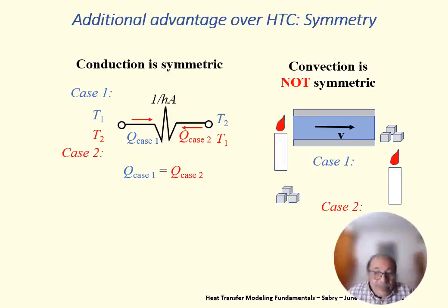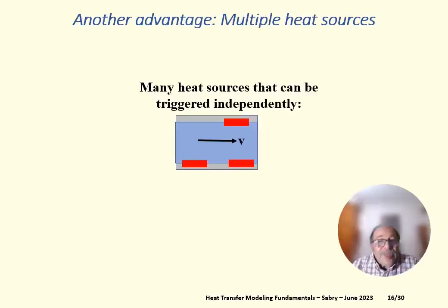By the way, the matrix I have obtained using the Green function that I have developed is a non-symmetric matrix. It exactly reflects this non-symmetry relation that H fails to capture. H is a resistance that is a symmetric element. Convection is not a symmetric issue. So modeling using H is wrong, or not sufficiently accurate. I mean, it's another way of saying it.